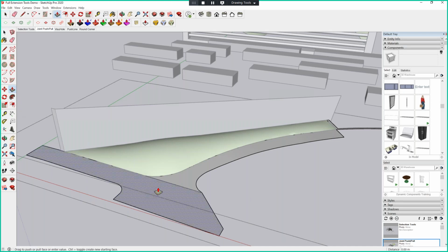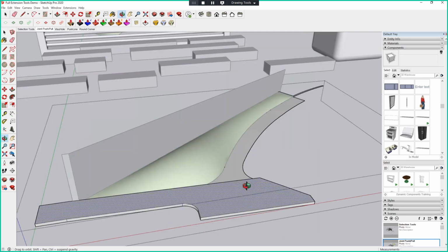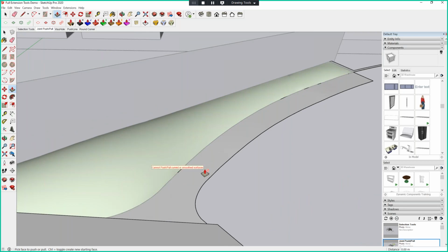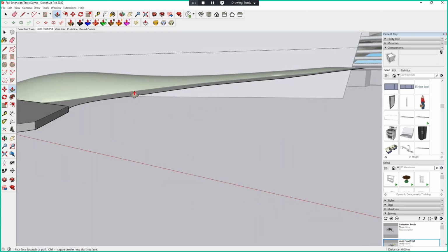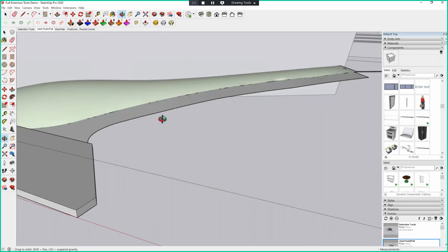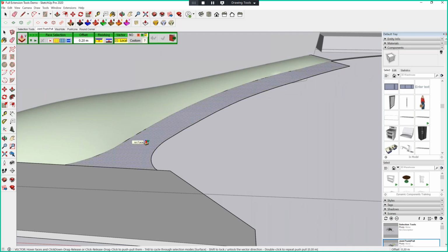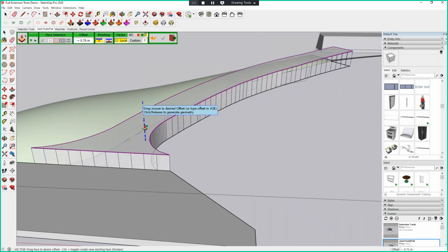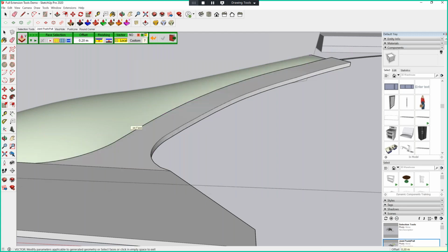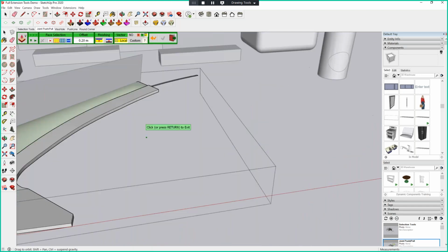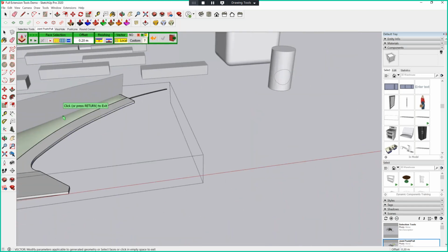And you want to create a curb of maybe 0.2 meters. You can create that with the flat surface using your push pull, but you realize you cannot replicate that on your elevated or curved surface that you have here, because we are not allowed to do that using our push pull tool. So this is where the vector push pull comes in. If I select it, you can select this face now, and you can bring it up the blue axis a total of 0.2 meters. So that's the function of your vector push pull. It allows you to create curves and 3D modeling for your landscapes, for your curved surfaces.